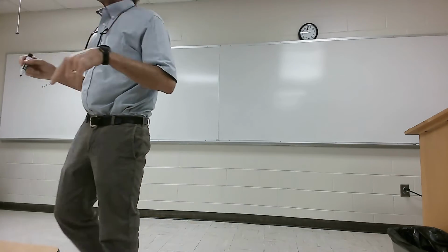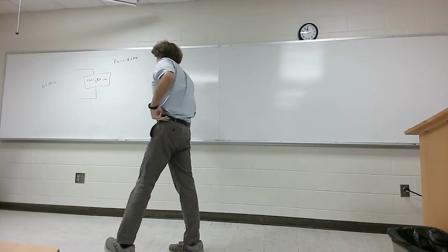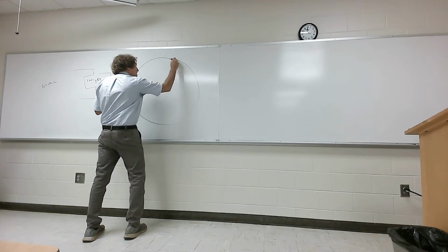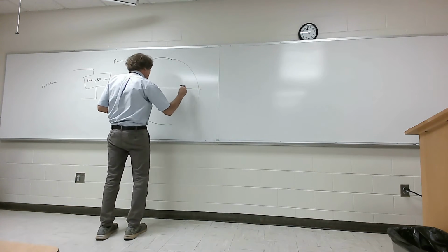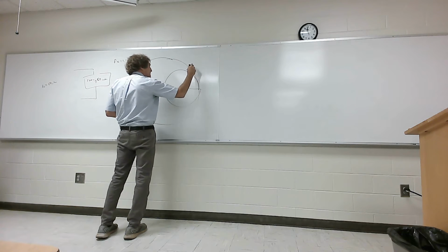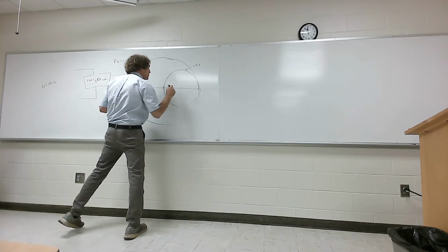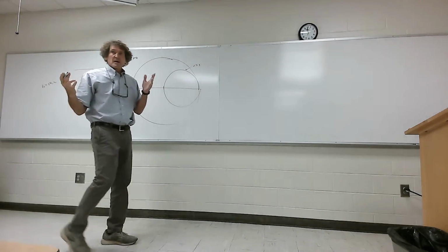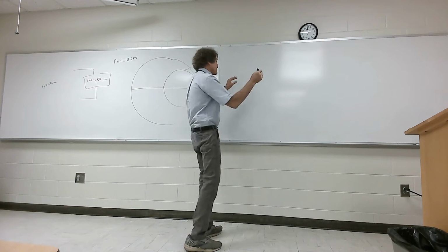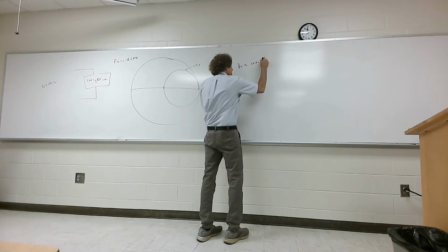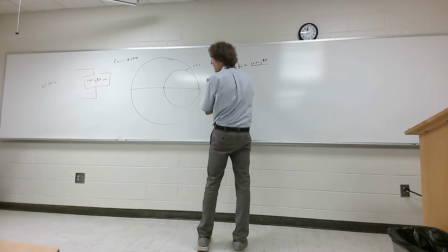All right, now when we do this one, let me draw my pseudo-Smith chart up here. That's the r = 1 circle. First thing I have to do is what, class? Right. So we get zL equals (100 minus j80) over 50.